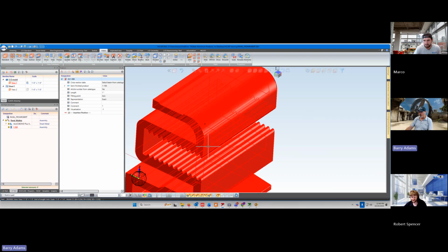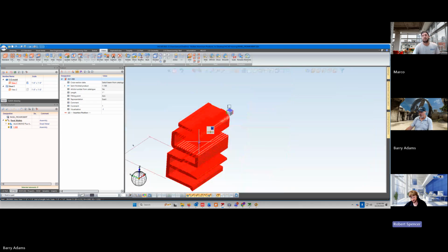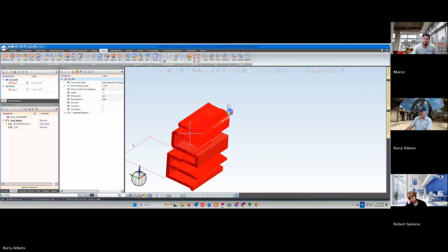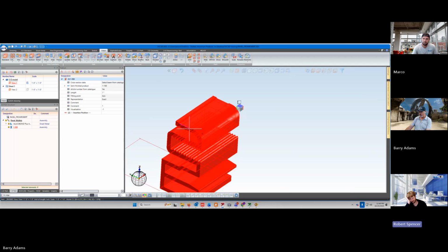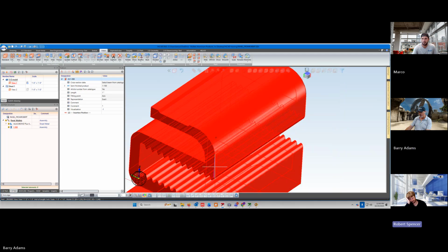Okay. So then I would zoom in here and just select an edge like this one. Remember, how do you calculate a theoretical edge? You need to call up that command. So you got to go to Enter. Press enter. And find the one. There it is. Now give it 2 edges, and here's where the orange glow becomes a little obnoxious. But if you zoom in there, you can indeed select. I would pick that one. Well, and this one. Either one there should get you the same place.